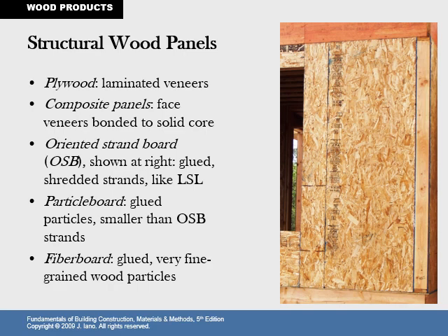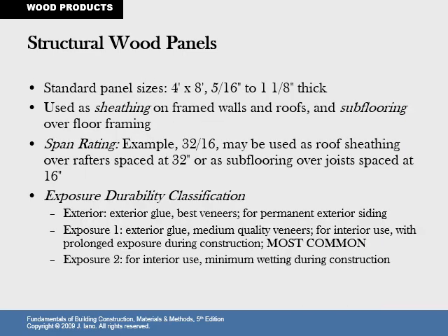Shredded strands like LSL, the particle board, glued particles smaller than OSB strands, fiberboard, glued very fine grained wood particles. Structural wood panels. Standard panel sizes, 4 feet by 8, 5/16 to 1 1/8 inch thick. Used as sheathing on framed walls and roofs, and subflooring over floor framing.